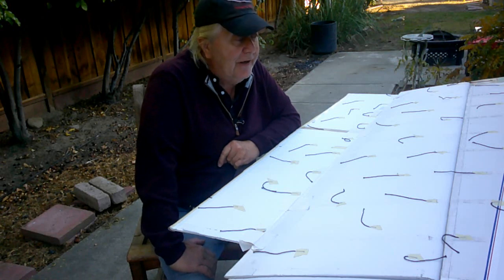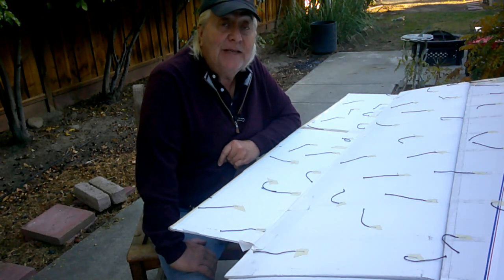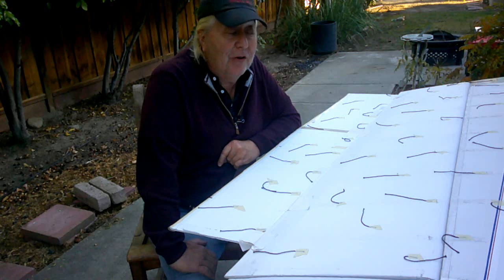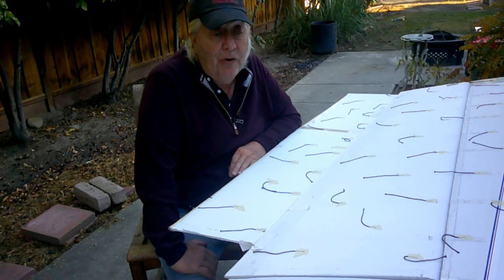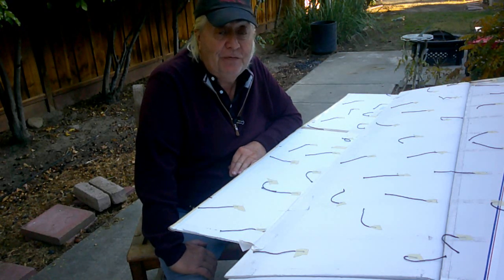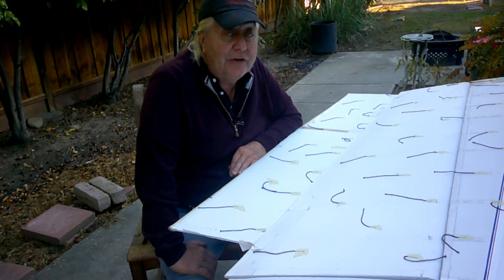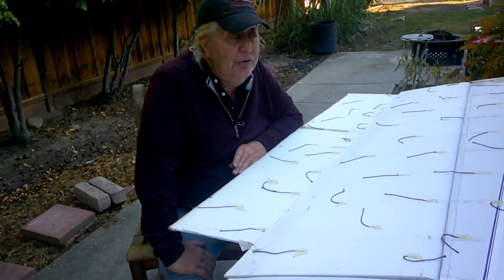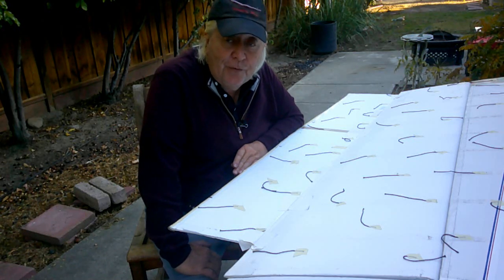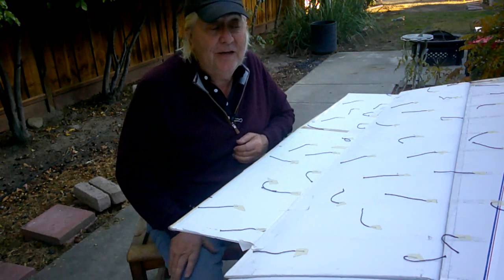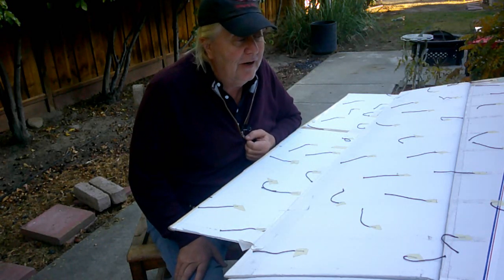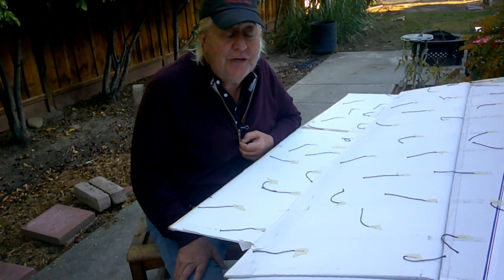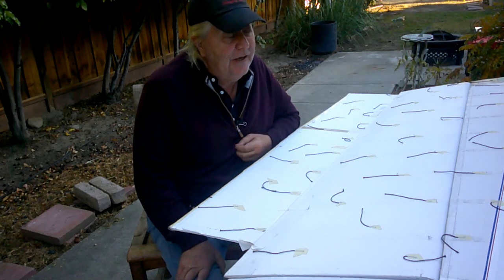And right now my current thinking is that might be the best answer overall in terms of balancing all of the parameters. I know it gets a little boring. Every single foot-launchable flying wing out there would be constant chord. They'd all look identical. But we're working in a design zone where there's very little room to make changes that increase performance without ruining something else entirely, and you end up with an unusable aircraft. It's quite an interesting situation and a challenging design.